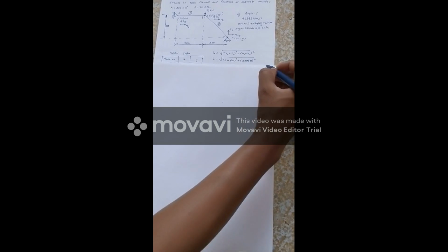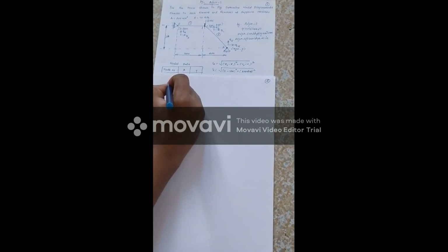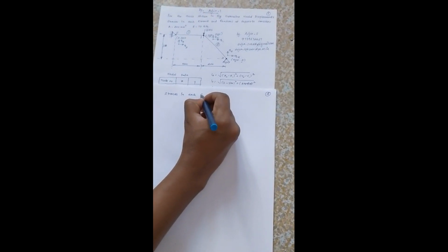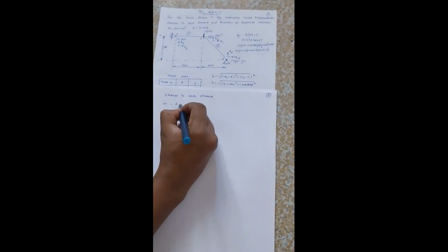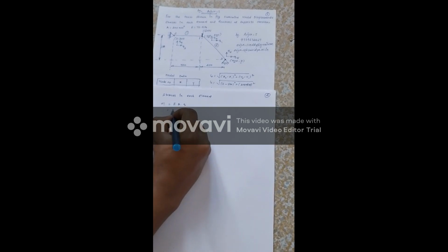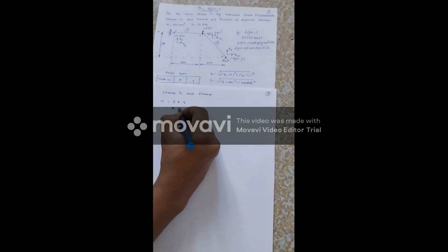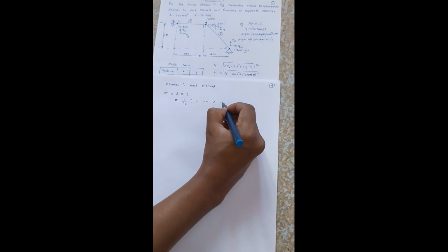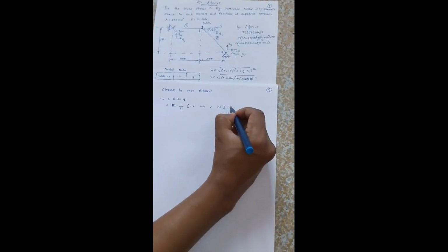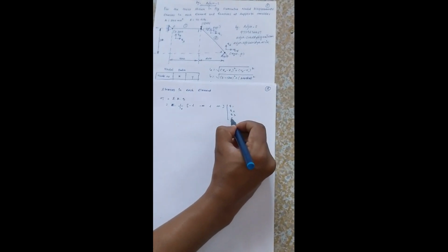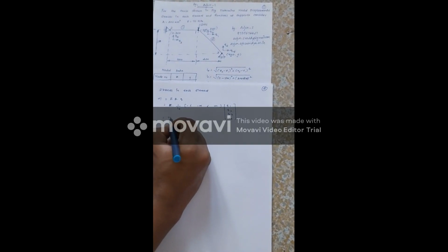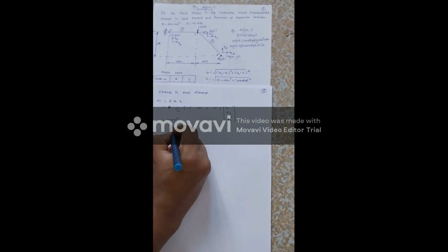And in order to find the stresses in each element, sigma 1 is equal to E into B into Q. So we write E as it is. B is 1 over LE times minus L, minus M, plus L, plus M. So element 1 will have nodal displacements Q1, Q2, Q3 and Q4. So Young's modulus of element 1 is 70 into 10 power 3. Length of the element is 500.